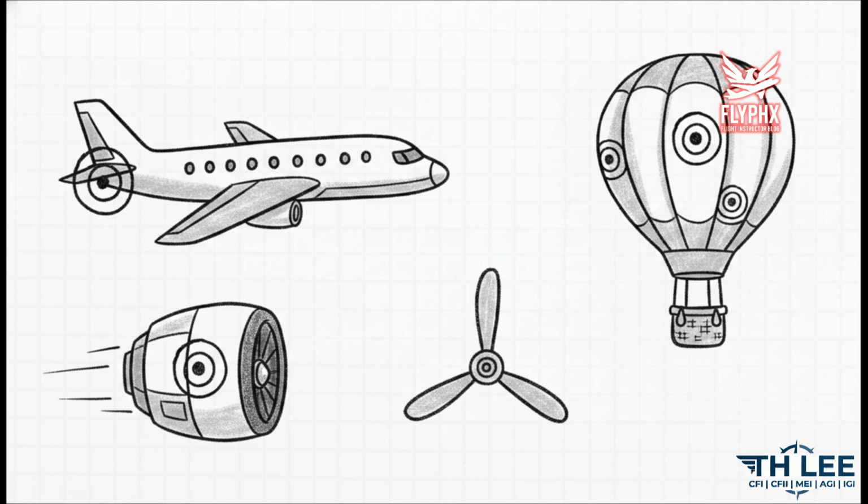Engines demand their own accessible fireproof plate, while propellers, blades, and hubs must be marked using approved fireproof methods, but specifically on a non-critical surface so we don't introduce stress risers. And for you balloon pilots joining us, the plate goes directly on the envelope, with additional permanent markings required on the basket and the heater assembly.